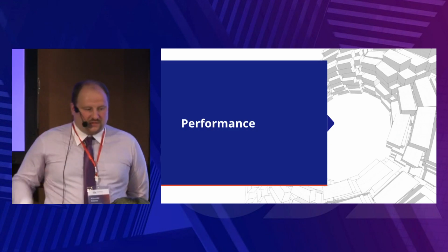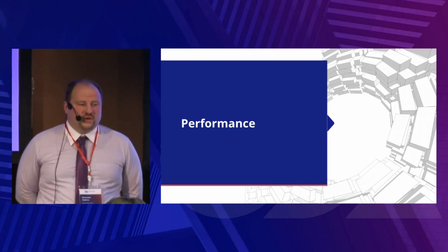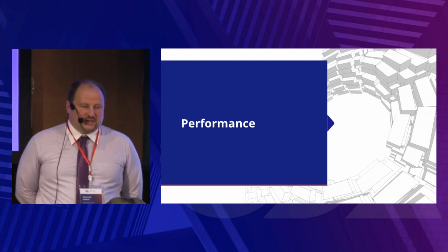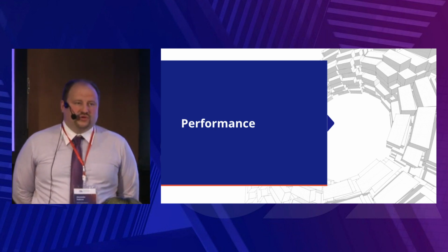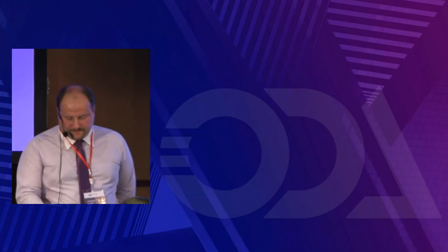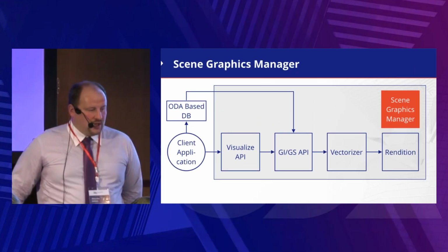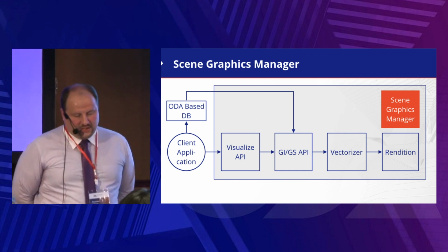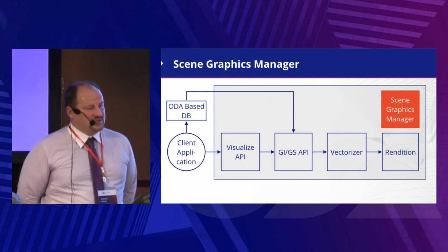The root task from the rendering performance point of view is minimizing the number of calls to the graphics software. This means that some geometry primitives should be merged in order to organize them by common attributes. Now such an ability is provided by a new layer, which was added to the rendition block inside the Visualize SDK.